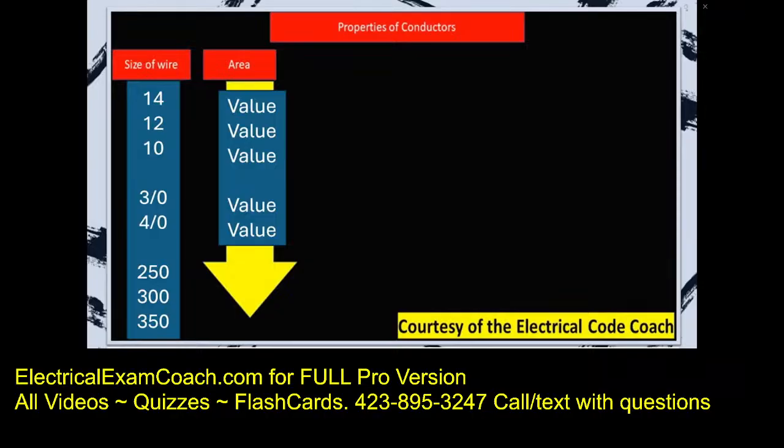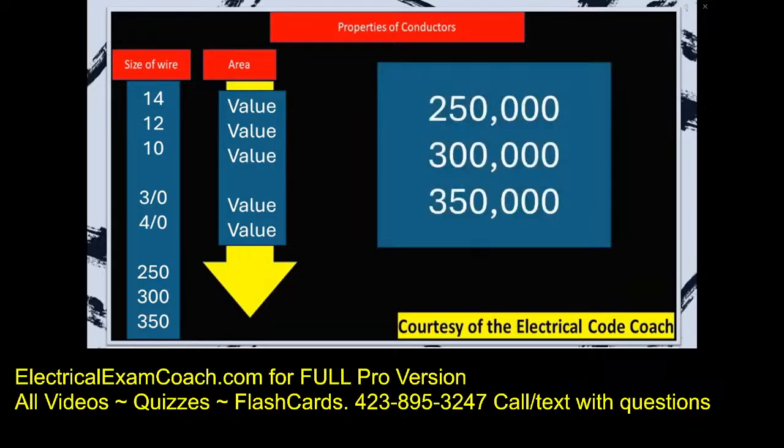You'll notice when you get down to 4/0 that the values stop. And the reason is because the left-hand side of this table, the 250, 300, and 350, are already showing you what the circular mils are in kcmils. So we have 250,000, 300,000, 350,000. So once you get past 4/0, you're going to get into 250, 300, 350, and all you have to do is add on the 3 zeros.